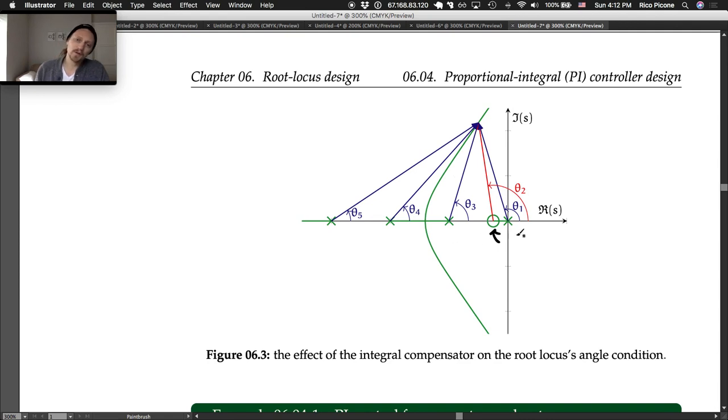So if you look at the root locus here now, then you have 0 root locus, and then you have locus between these two, the compensator pole and the compensator 0. No locus, locus, sort of like the original one, no locus, and then locus. You look at 3 zeros at infinity, the asymptotes go off in the same angles, and the same stuff occurs. So there's really not as much of a difference now. So now we've got this nice locus going similar to how it was before.